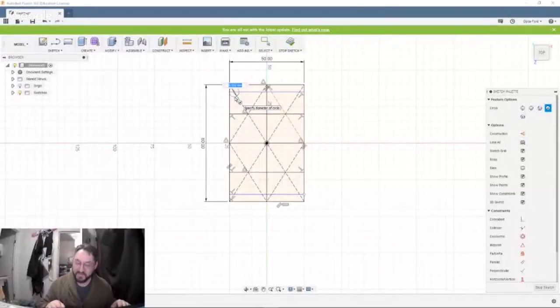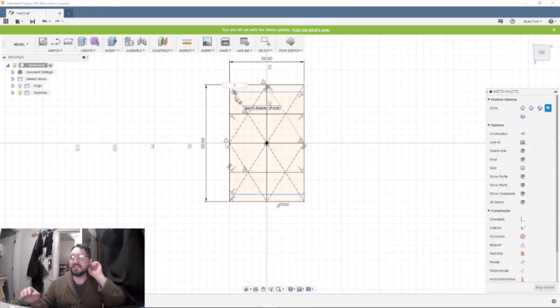All right, so we're going to go 3mm. It still seems a little bit close. I'm kind of worried about blowout is what I'm worried about here. So I may move that over a little bit. That only gives me about 2mm of perimeter. So when you put a screw in there, it's probably going to try to push out the plastic.